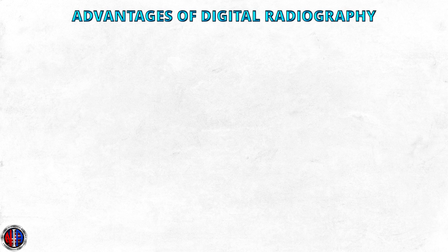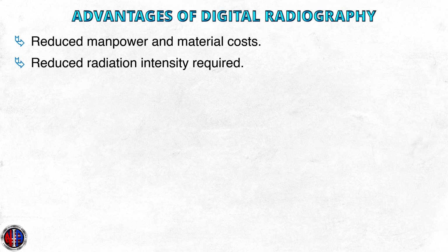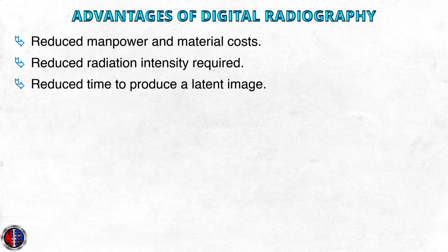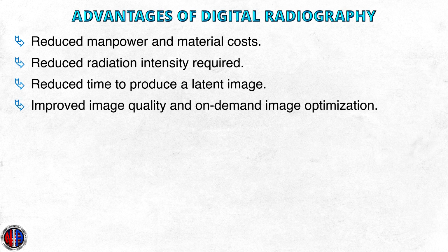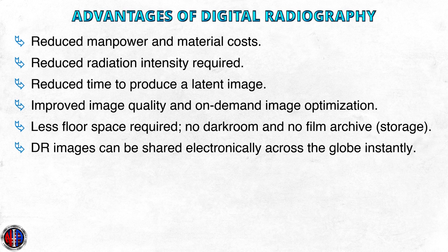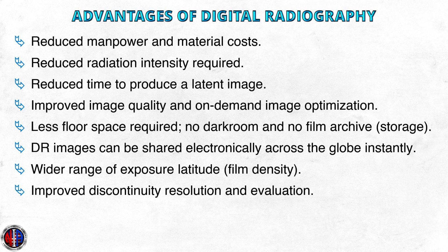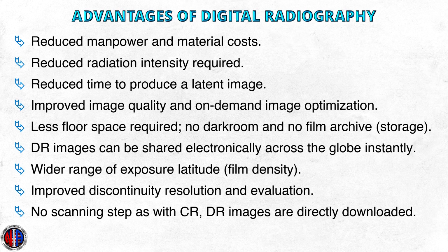Advantages of digital radiography: reduced manpower and material costs, reduced radiation intensity required, reduced time to produce a latent image, improved image quality and on-demand image optimization, less floor space required, no darkroom and no film archive or storage. DR images can be shared electronically across the globe instantly. Wider range of exposure latitudes. Improved discontinuity resolution and evaluation. And no scanning step as with CR. DR images are directly downloaded.